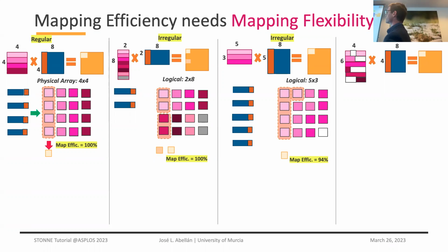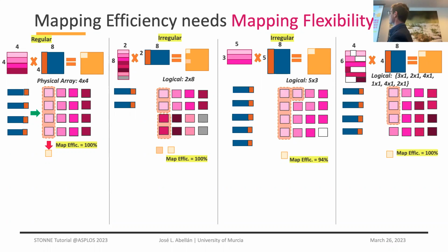In terms of irregularity, when you cannot accommodate all the matrices for one or 2 of the dimensions, here 2 because we have this systolic array, what you can do is, okay, let's put those elements that don't fit in the idle processing elements. This is when we enable this ideal mapping flexibility. Or when we have the sparse computation, okay, let's map only the non-zero elements onto the processing elements in the systolic array. And then we are achieving very high, almost in this case, 100% mapping efficiency.